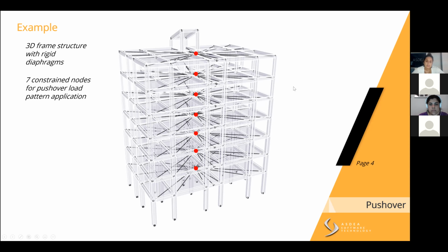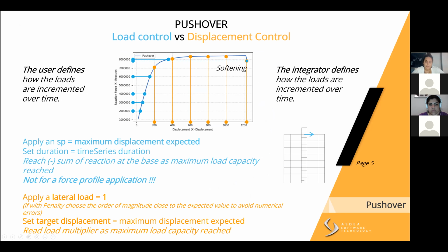There are 2 ways that nonlinear static analysis can be carried out: load control and displacement control. We already discussed this in week 10, but just to reiterate, in load control, the users, so you guys, define how the loads will be incremented over time.